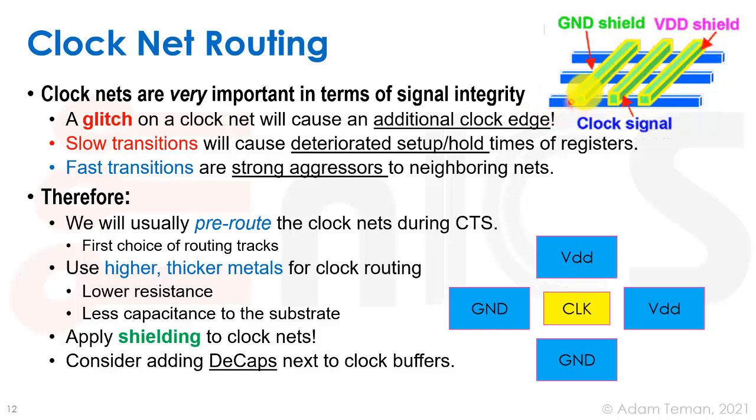What that means is that the actual area where we have a cross between two adjacent metal layers in the vertical direction is going to be really small. We just have this little square here. So the coupling capacitance is probably not very big. Another thing is that the interlayer dioxide might be very thick, so we might have a big distance. So I don't think in most cases we're going to route these top and bottom metal layers around our clock nets. In fact, it's really not going to be done that often.